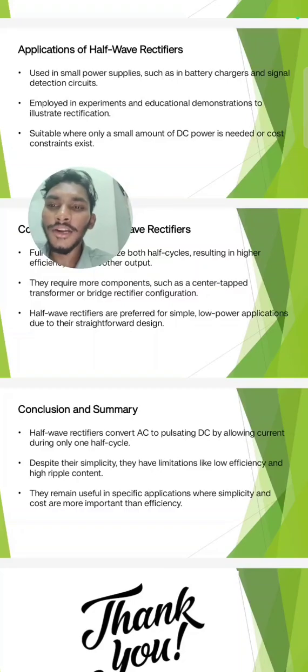However, in practical applications, half wave rectifiers are rarely used due to poor efficiency. Instead, engineers prefer full wave rectifiers, center tapped or bridge, because their efficiency is higher.